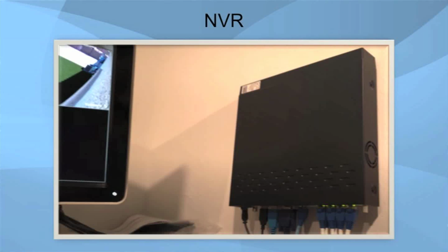Then we move to the next important device that is required for CCTV installation, that is the NVR or network video recorder. There is another type of video recorder called DVR, which is digital video recorder. Both of them work in a similar manner, but the NVR or network video recorder is one which can also be used to integrate the system through mobile communication or other internet related connection and equipment. So this NVR is the location where all the videos which are captured by a number of CCTV cameras installed across the house can be connected.